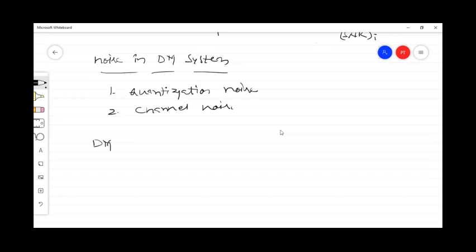In delta modulation system, we know the signal is transmitted in the form of single coded pulses. Single coded pulses means either plus delta or minus delta. That means either 0 or 1 in terms of bits. Otherwise, in terms of voltage levels, it is either plus delta or minus delta. So in delta modulation, the signal is transmitted as plus or minus delta.